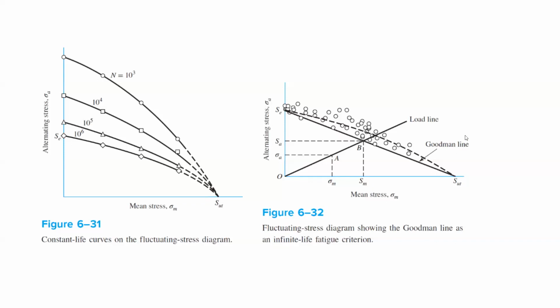And so ultimately, we have to have some way of predicting whether a material is going to fail at these given loading conditions, right? There are a few different criteria that have been developed by material scientists over the years. It's essentially limit lines on this mean stress and alternating stress plot. You can plot these lines just as an approximation without having exact testing data for the material. These dots are actually how the material would fail if you tested it for some n number of cycles, right? But you can predict it using these different equations, which produce either the dotted line or the straight line. It's not too important to know the names, but typically the Goodman criteria, or the straight line, is a really good way of assessing if you're going to fail under fatigue. As long as you're under this region, this triangle here, then you're good.